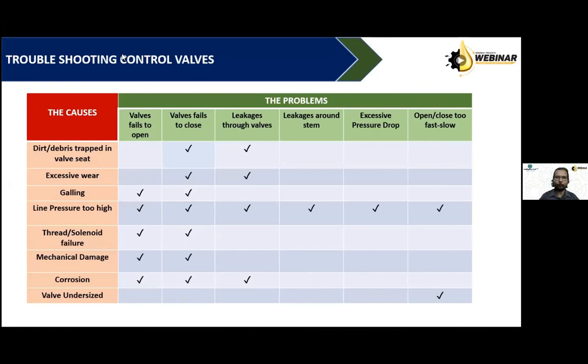Mechanical damage, corrosion, valve undersized. Sometimes it happens because if valve has no factor of safety like 1.5 or 2, then a very small contaminant or very small damage to the valve will lead to inoperation of the valve.